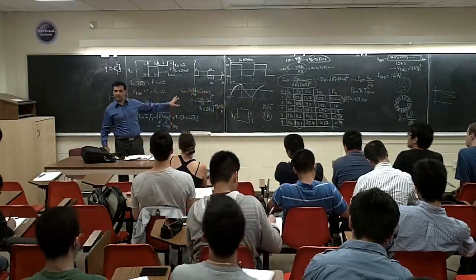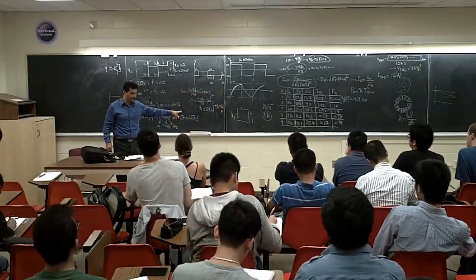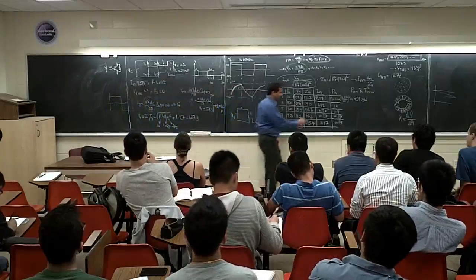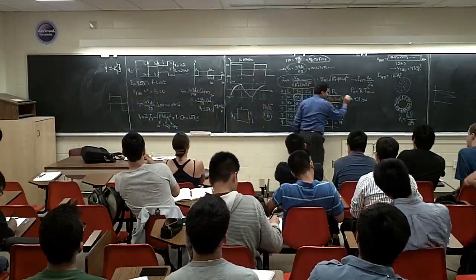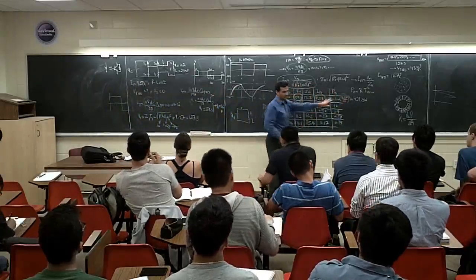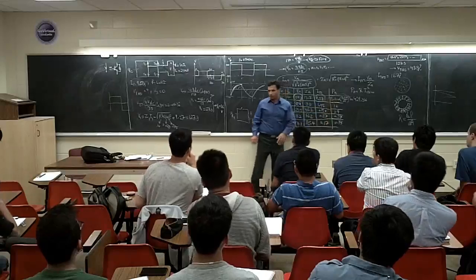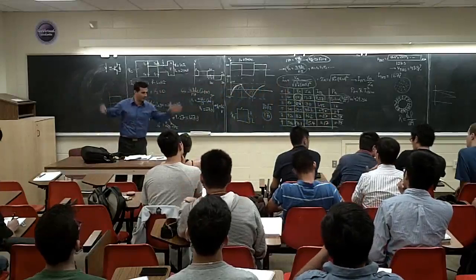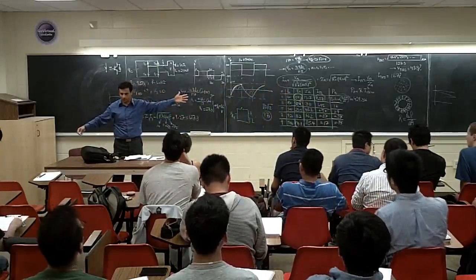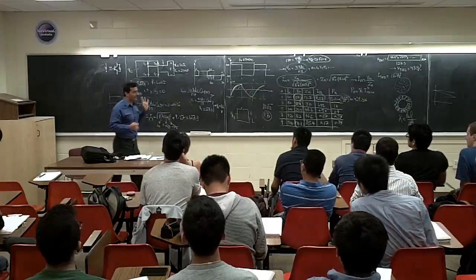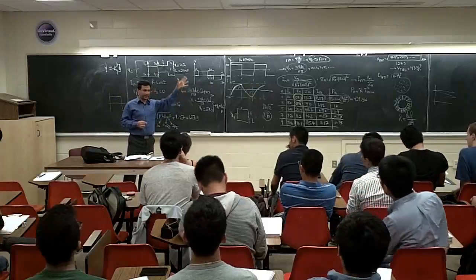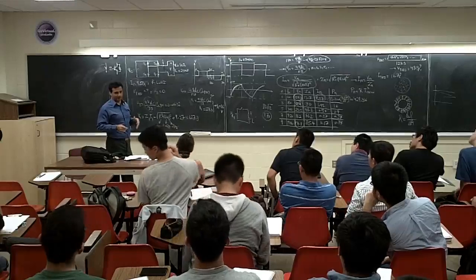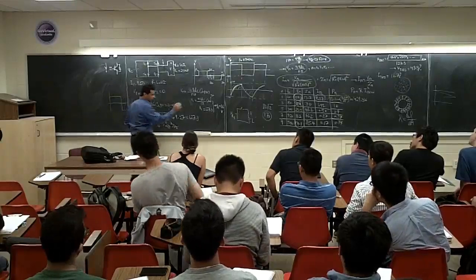See? You got rid of the third harmonics at the cost of what? A higher DC bus. I am getting the same current output, and the same power output. So I have the same input and output current, which means the same power. The inverter I'm building is going to give me almost 500 watts, and I have fewer harmonics. We're going to calculate the voltage THD and current THD again. Definitely they're going to be better because we're getting rid of the third harmonics. But at what cost?